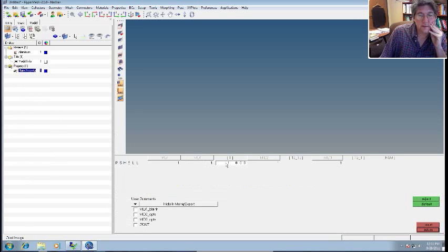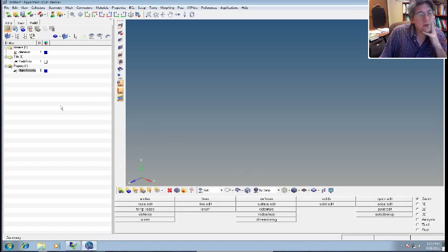It's fully defined, it's got the thickness defined, and then it has the material assigned to it, okay? You can see if we hit mid 1, we can add different option fields. You can do a continuation card and put in the next line. That's optional, but we won't do those, so we'll just leave it at the basic one-line P-shell definition. We won't use the other optional lines, okay? All right.